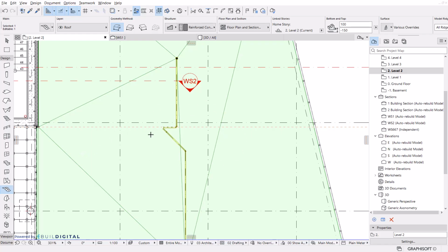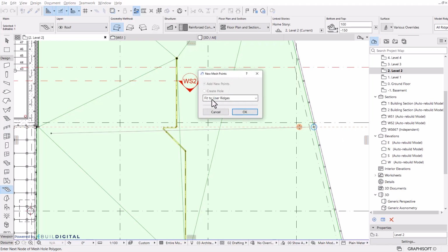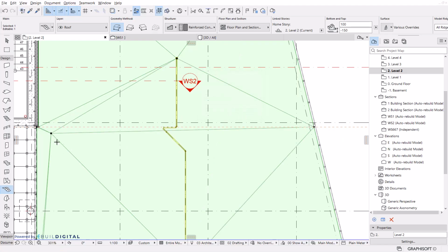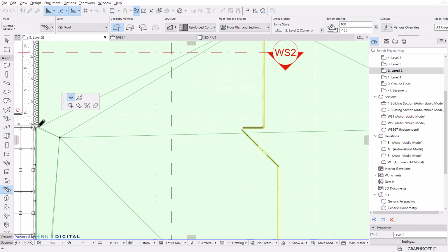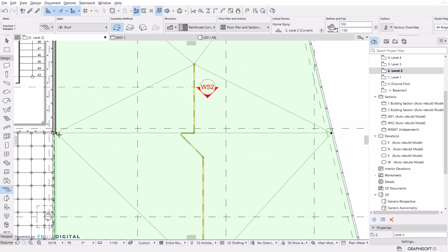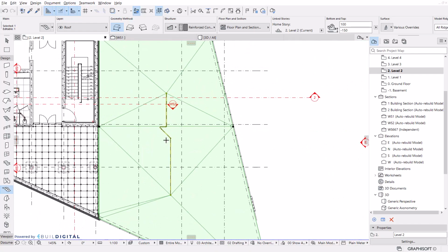And again, you need to have the element selected and have the mesh tool active. So what I'm going to do next is simply click close, but not on top of the hotspot, not even on top of the guideline, but rather outside. And the last point should be right on this node where the guideline intersects the edge. Now that's going to be a line that is going to act as a ridge. And then let's move this node, not by moving it in elevation, but rather move the node to the corner right there. And then you'll have split these two sides.